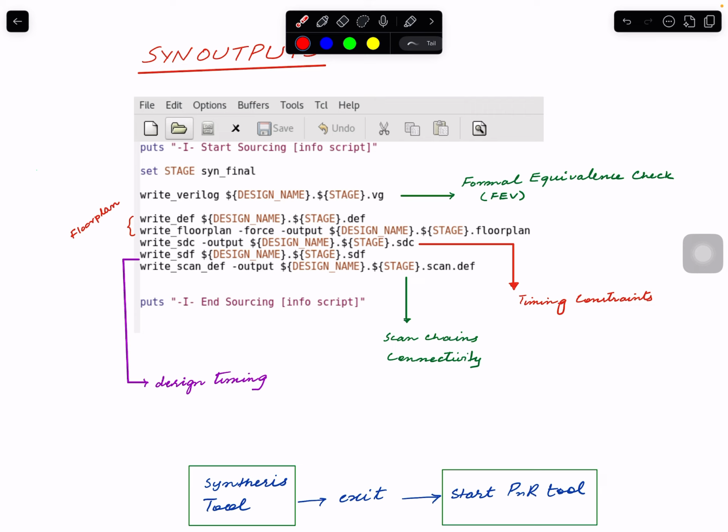So what we do is, some flows on some projects or in some companies are more Tcl based. They always take their inputs at each stage as a Tcl file. For example, they would create one Tcl file that they will give to synthesis, place and route, placement, CTS, routing, and then for final sign off. Some project groups or companies tend to use SDC files. So very first time they might have a Tcl, but then in their flow, they just stay with the proper SDC format. Every tool stays with that.